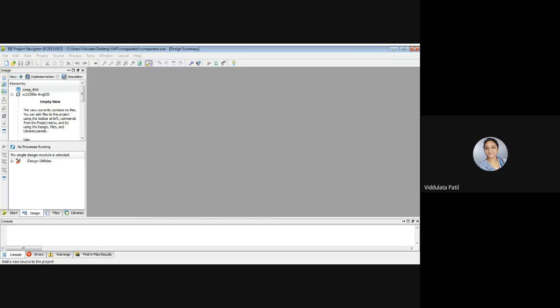Okay, so that means A is the input port, which is 3 down to 0. Also B is the input, and the MSB that I am going to select is 3. So that means it is 3 down to 0. So A and B are the 4-bit inputs.